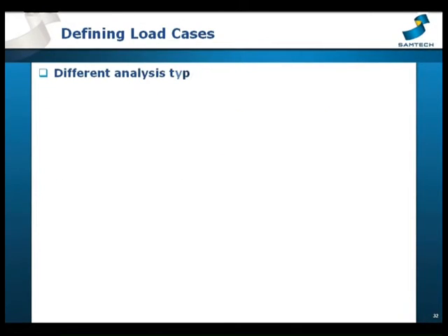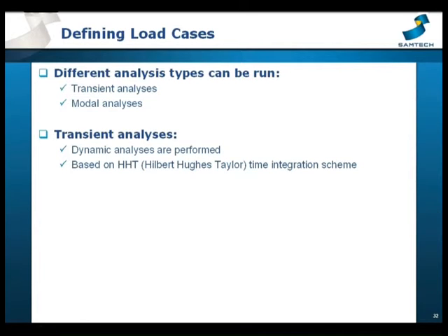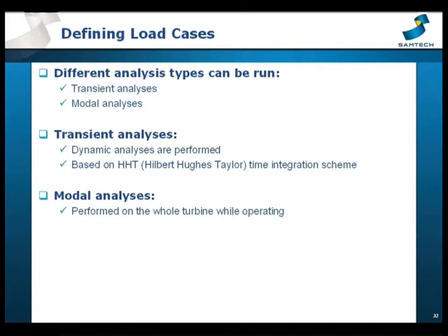Based on these load cases, users can run two major types of analyses: transient or modal. Transient analyses correspond to the computation of the turbine's dynamic behavior. They're based on the Hilbert-Hughes-Taylor time integration scheme. Modal analyses, on the other hand, are performed on the entire turbine while operating.